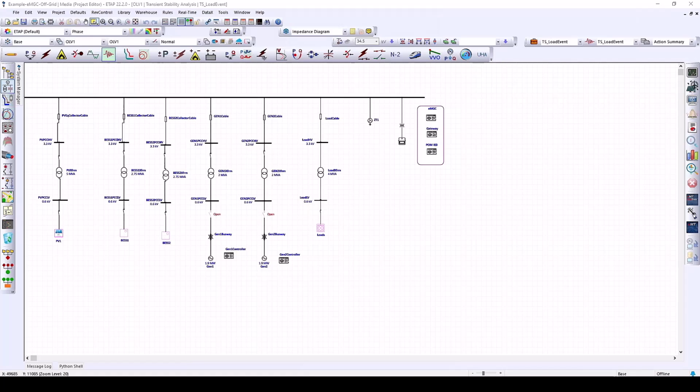Here we have an example of an off-grid microgrid with 5 MW PV and 2 energy storage systems, each with a 2.6 MW power rating and a capacity of 9 MWh. We assume that the peak load in this system is around 1.8 MW. Besides, we have 2 DGs that can work as a backup to feed the load in emergency cases.